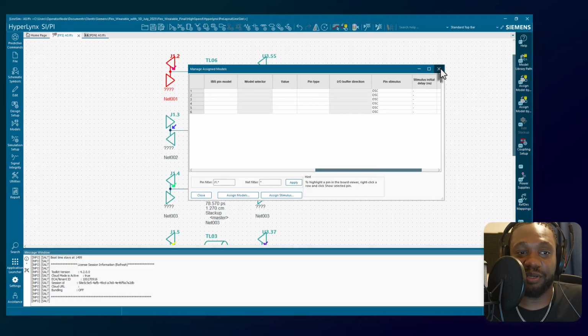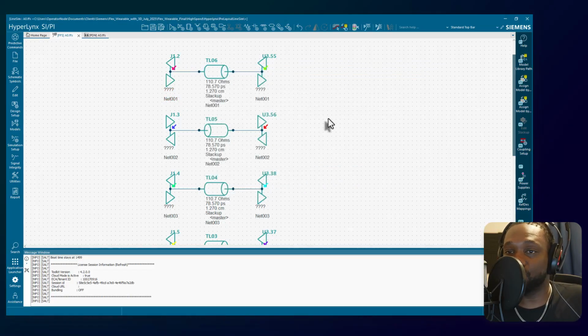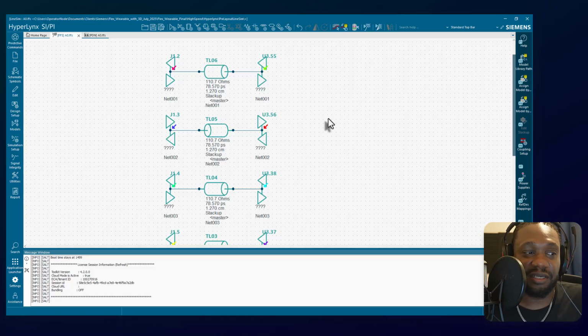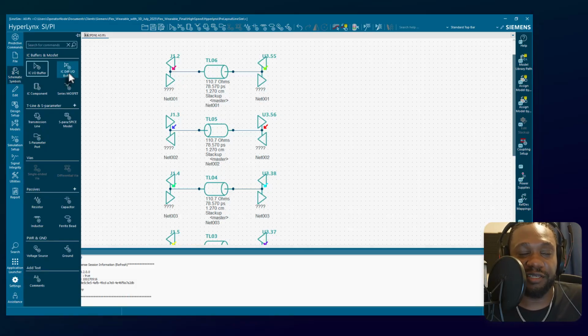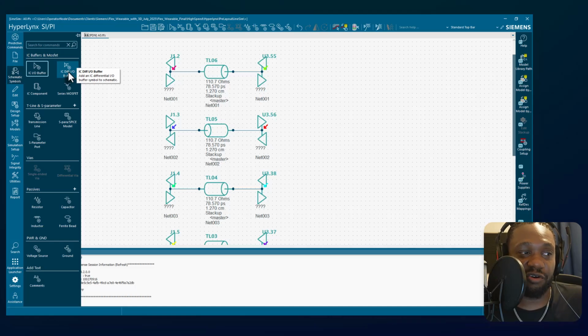It's literally HyperLynx. If you're not familiar with HyperLynx, it is a tool that lets you do in-depth signal integrity analysis. It has, I don't know if it's a 2.5D or 3D field solver, but it's very good and easy to use. Then it got integrated and wrapped up into the Xpedition software suite, so it's part of that. I don't think you can get it separately.